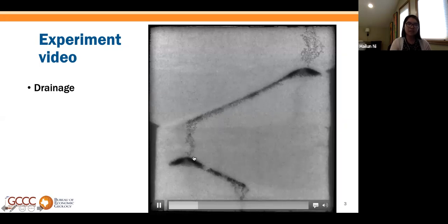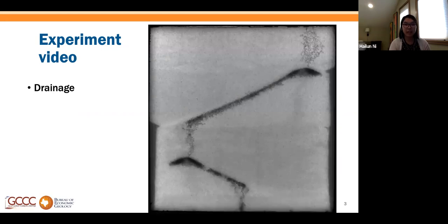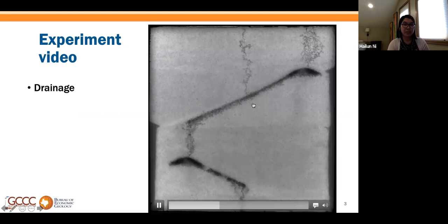After the establishment of this new finger flow path, we see that the non-wetting phase is now coming out of the lower capillary barrier region in these distinct gulps or pulses. As the pulses go through the domain, we can see that with each pulse, actually slightly more pore space is invaded by the non-wetting phase. And as these pulses keep going through the domain, eventually right here, we actually see this unexpected early breaching of the upper capillary barrier by the non-wetting phase.